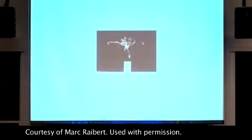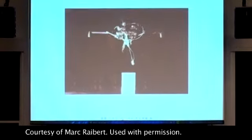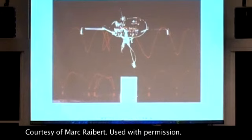Here we go. So this little robot, you can see that's tracing its foot. This up here is tracing its center mass, and you see how center mass actually compresses right above the foot. And so that's what you expect here. It lands and squishes down. So instead of when you're walking and you vault over this leg, like you think about that rimless wheel, the center mass rolls up over its foot.